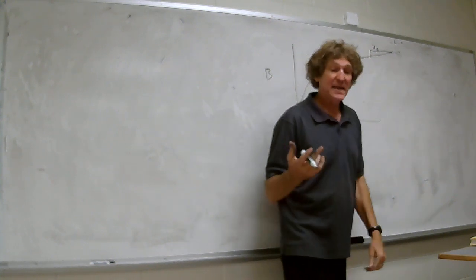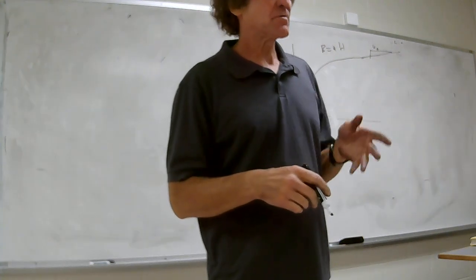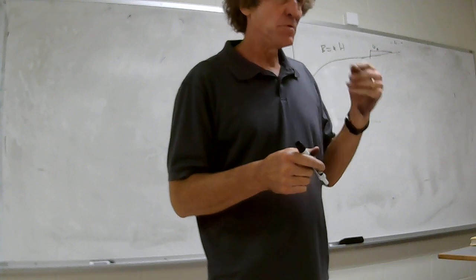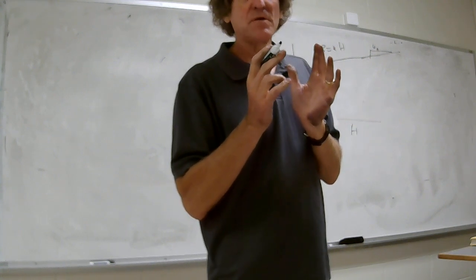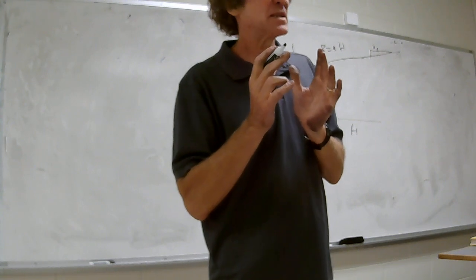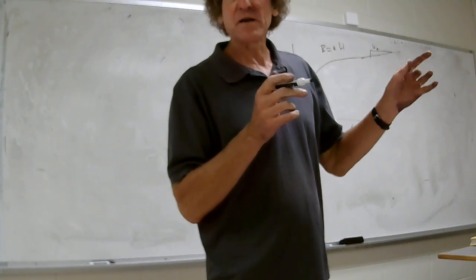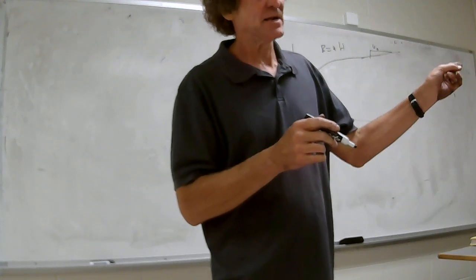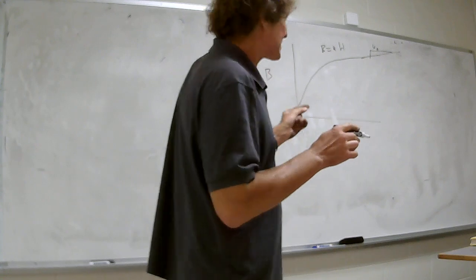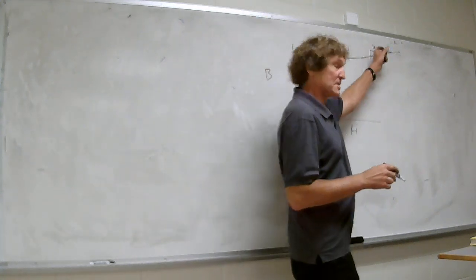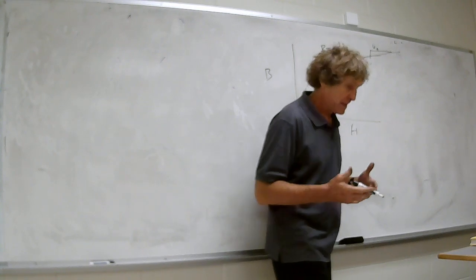Remember, magnetic energy is 1/2 B dot H, or 1/2 mu relative mu naught times H squared. Now that mu relative at the low end has a large value. But as you start getting larger and larger values of H, all of a sudden it gets saturated. You can't align anything after that. And now the increase in energy just has to do with this, mu 0. I'm just trying to explain it in a way that it's not.